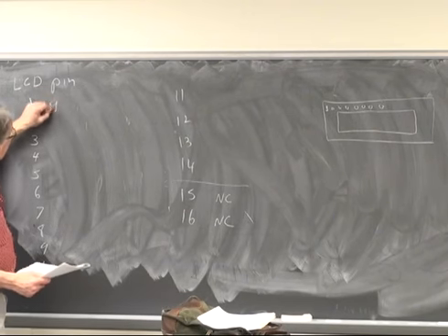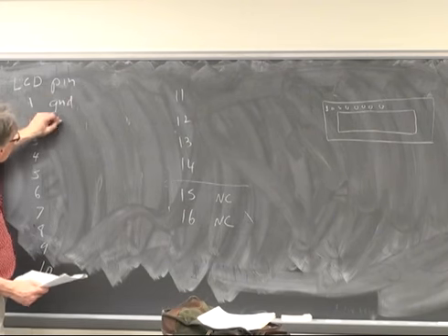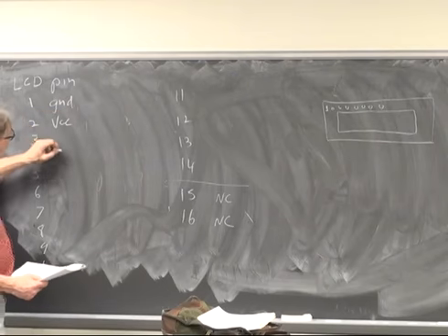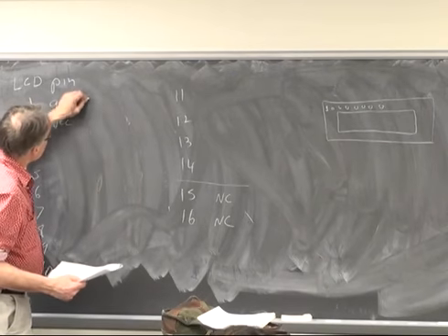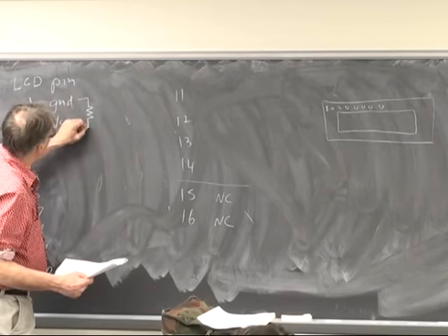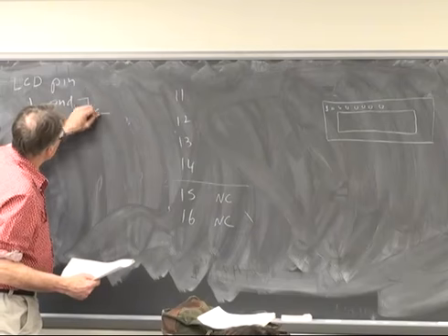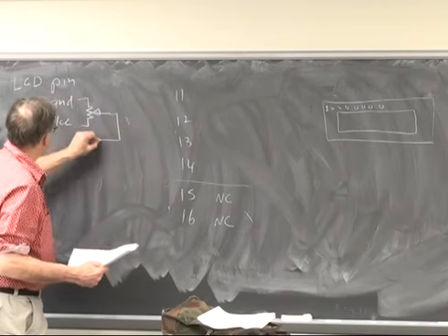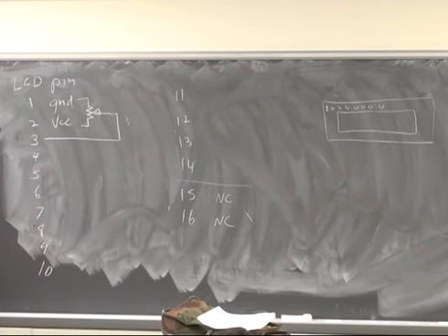Pin 1 takes ground. Pin 2 takes VCC. Pin 3 is the output of a potentiometer hooked between 1 and 2. It's a 3-lead device, trim pot.